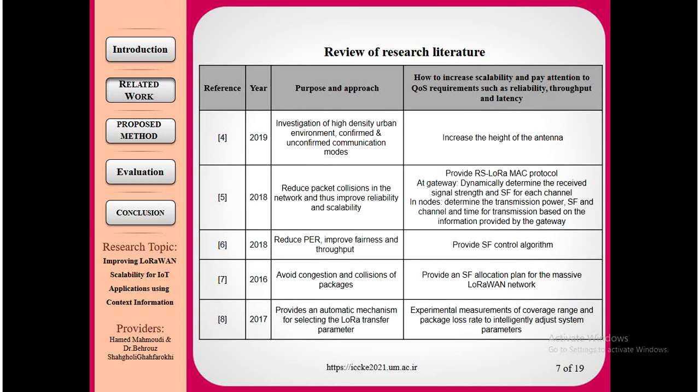In this protocol, what needs to be done at the gateway is to dynamically determine the received signal strength and SF for each channel, and what needs to be done in the nodes is determining the transmission power, SF, channel, and time for transmission based on the information provided by the gateway.